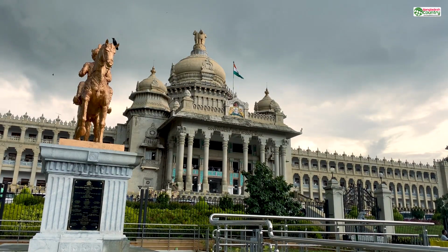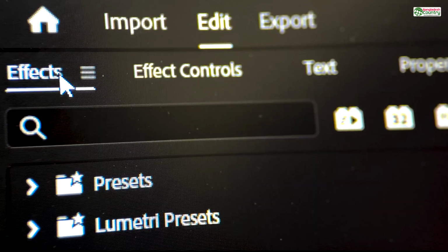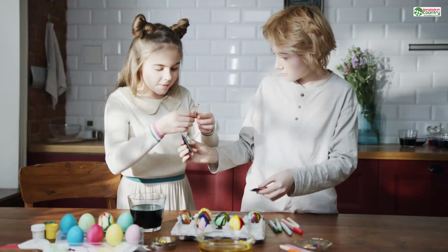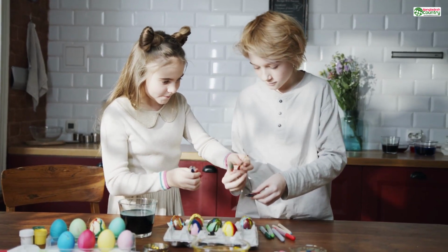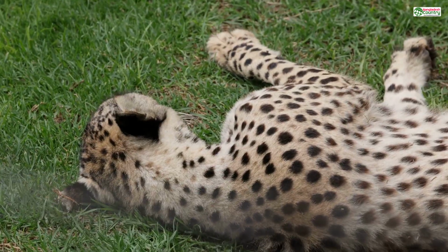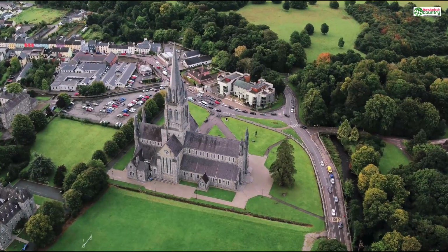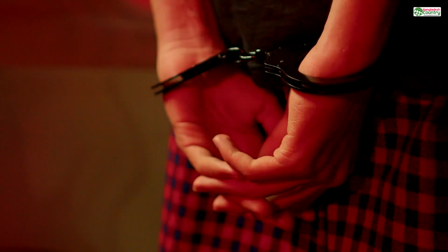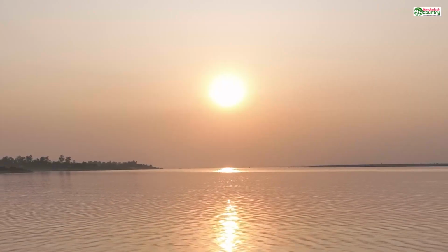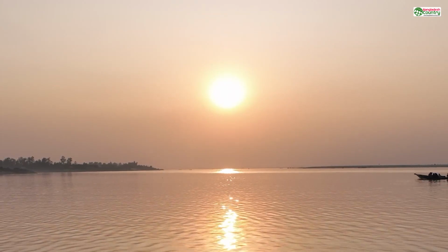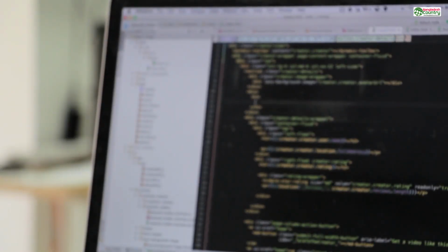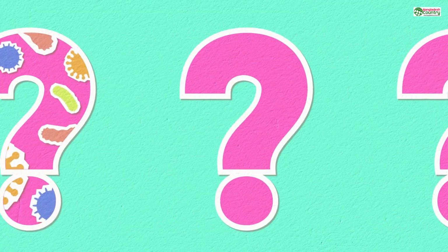Your software will also have a way to visualize these. Often, it's a setting that displays the direction of the normals as little lines or by coloring the front and back of a face in different shades. When you spot a section that's the wrong color, the fix is usually astonishingly simple. You select the offending faces and use a Flip Normals command. Or even better, you can often select the entire model and click Recalculate Outside. The software will look at the overall shape and make a very good guess about which side is supposed to be the exterior, flipping all the normals to point the correct way in one go.